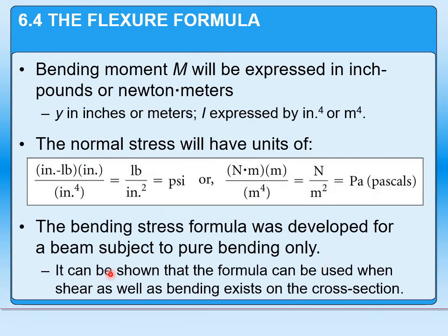So keep in mind that the bending that we've done so far has been developed for pure bending only, right? But it turns out that the formula can be shown to work whenever we're dealing with a situation, even if shear is there. So shear is another effect we'd have to take into consideration, but it doesn't need to be a pure bending situation for the flexure formula to apply.